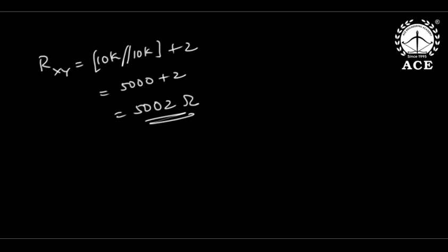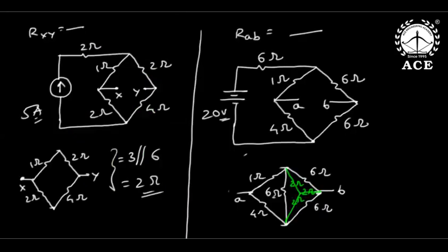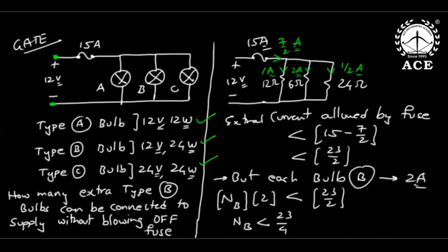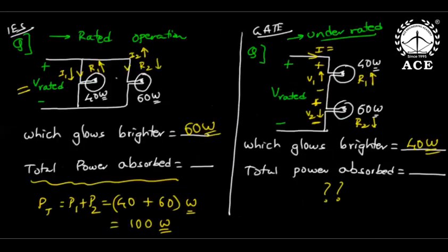Sir, in two questions you have given which bulb will glow higher, in case of series connection of bulbs. Sir, intensity of light depends upon the flow of current, no? Yes, of course, current is equal both ways, but voltage drop also will decide the power. Intensity of bulb does not depend upon current alone here. See, I square R is the heating effect.